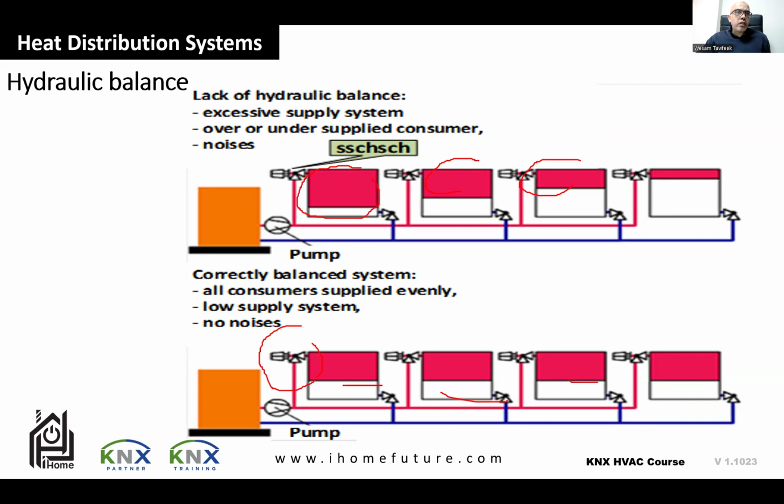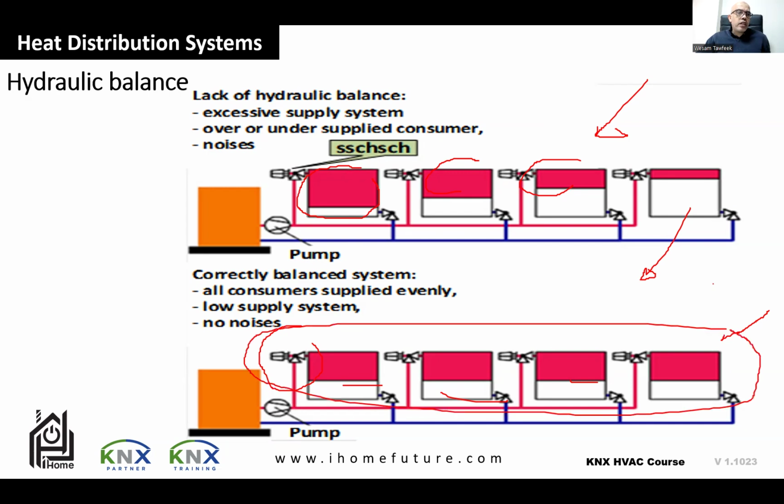So if heating systems are not hydraulically balanced, just like this case, no heat will reach the radiators at the end of the heating circuit. This one will have very little heat. Therefore, a hydraulic balance differential pressure, the one that we need compensation for, must be performed when balancing the heating. Balancing is the process of lowering the flow rate to the front or lower radiators in the building to make sure that the heat among the radiators is the same.